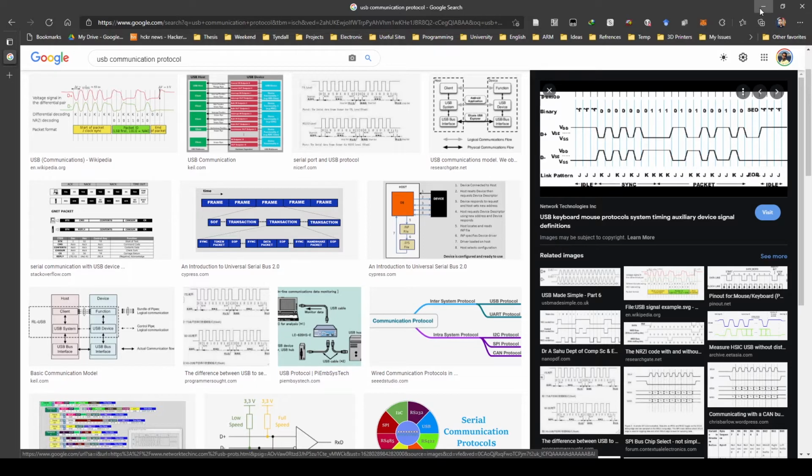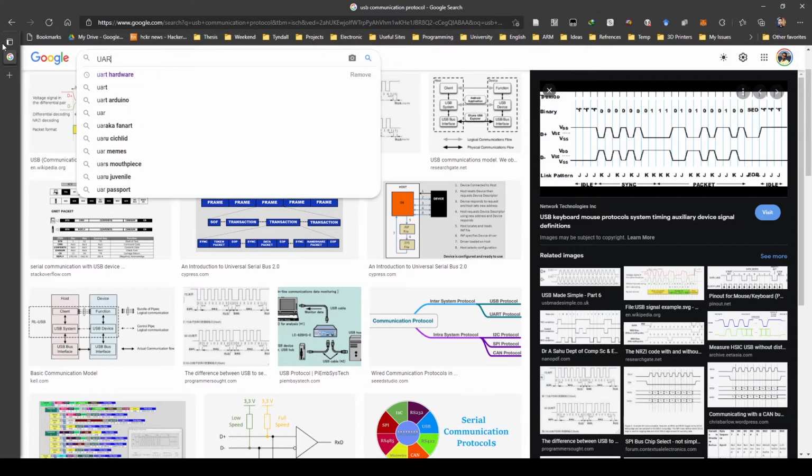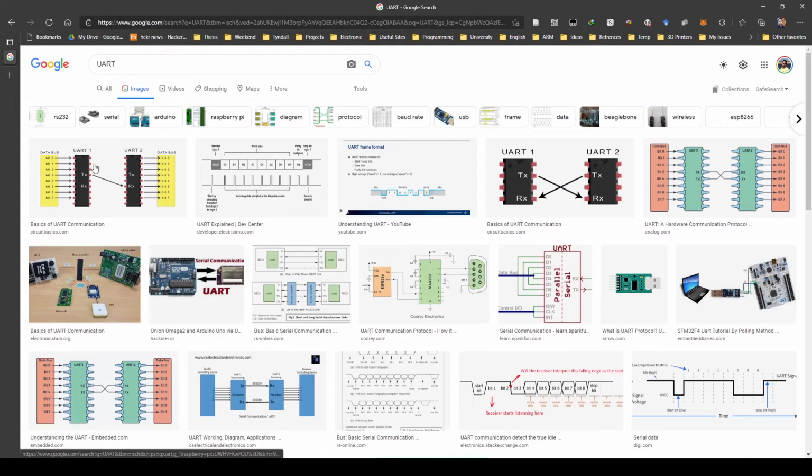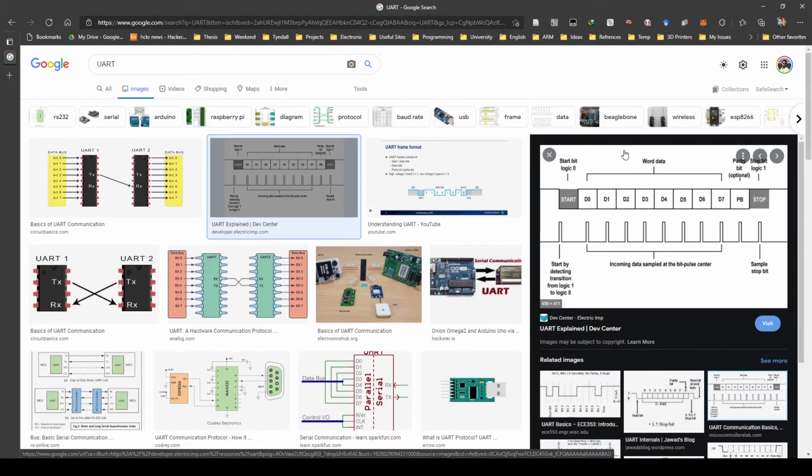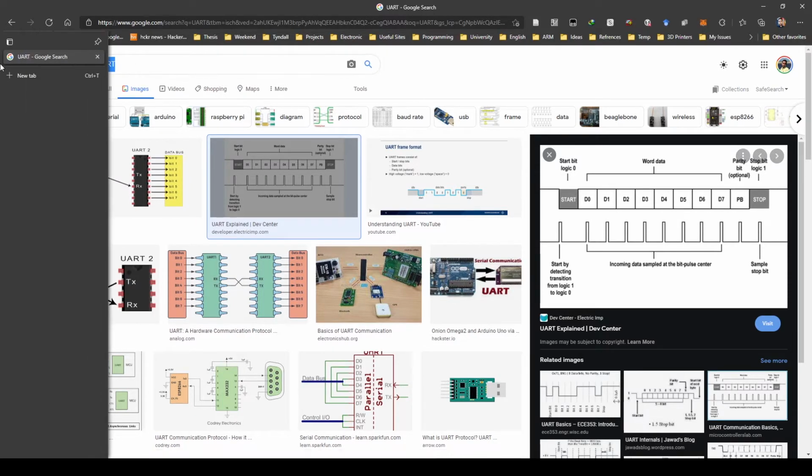So now let's go to the STM32 cube and configure our microcontroller for communication with the PC. So in the microcontroller case, we have the UART option, which uses specific rules for communicating with any device, not just the PC. But we also have USB.